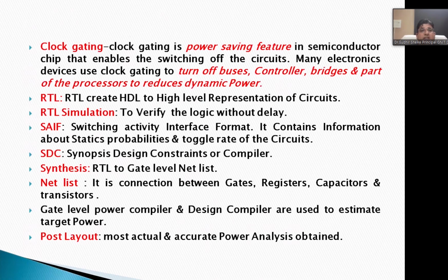By using clock gating, which is a power saving feature in semiconductors. As you know, we are using handheld devices like mobiles, and it requires that the power of the design has to be reduced. Whenever you are using a mobile, a number of blocks will ultimately be used, and those blocks are required to be controlled by using this clock gating technique.